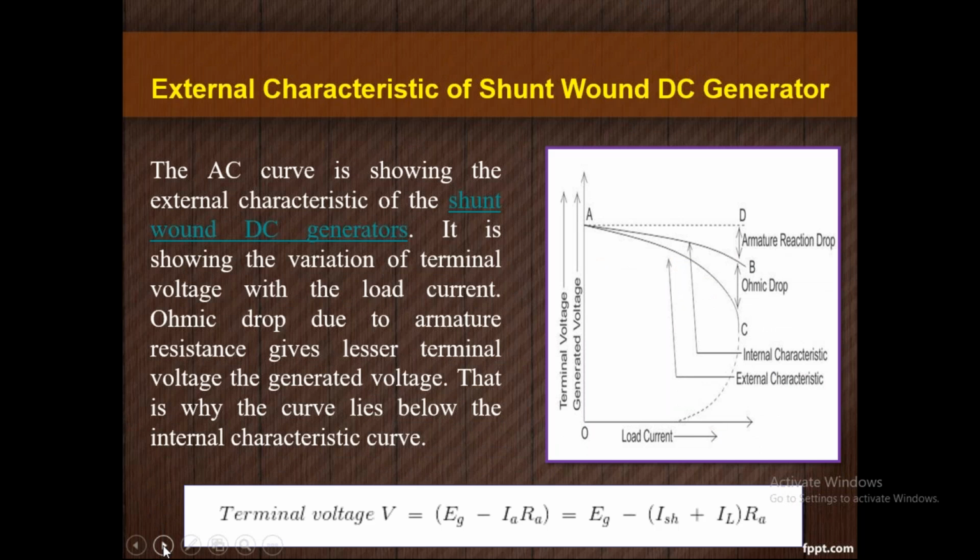Right. See here, how we can get how much voltage was dropped across the generator by using this formula. This formula represents how the EMF will be. This is the final voltage, and this is the initial induced EMF, reduced by this drop. When the currents ISH and IL flow through the windings, the drop will occur. So this entire term will be the drop, and the final voltage is 230 volts minus the drop.